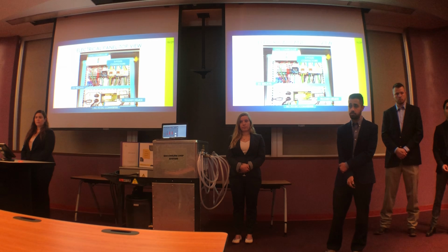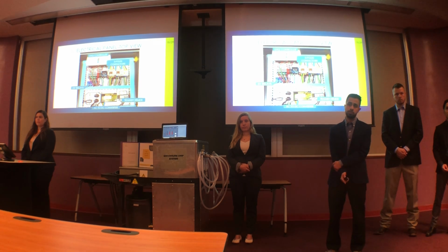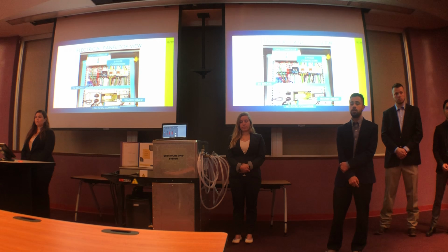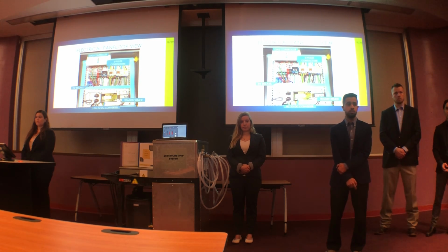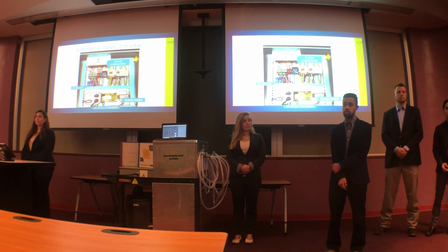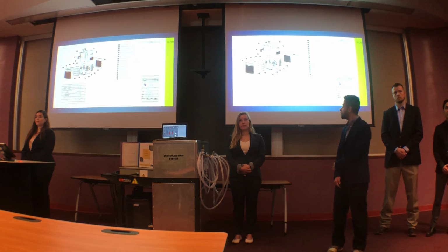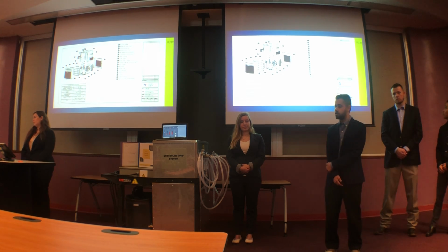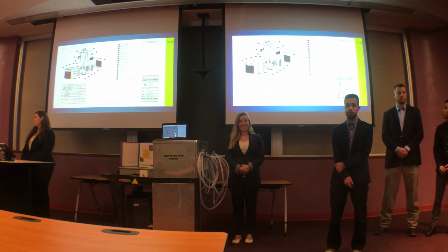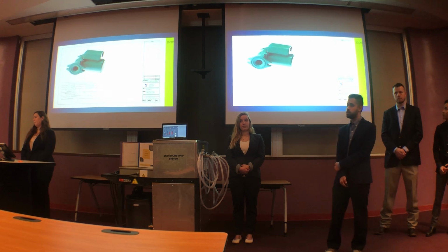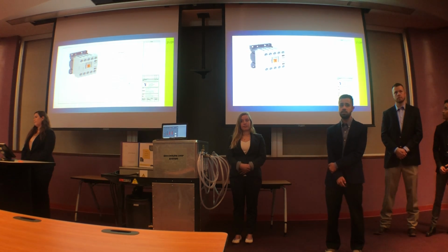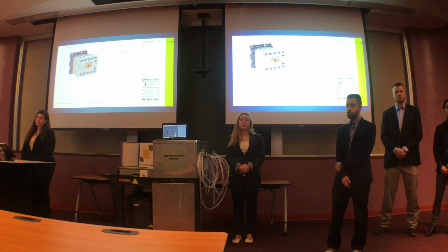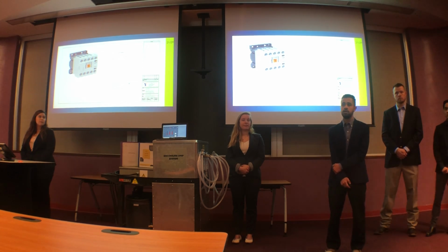And we also have a transformer to kick off the controllers, which control the chiller, the heater, and the pump. We also have a 24 AC to DC converter, which supplies power to the pressure sensors and the piping system. We also have complex specification components such as the chiller, and simpler ones such as the pump, and electric components such as the contactors. For more details, you can refer to the part manuals.